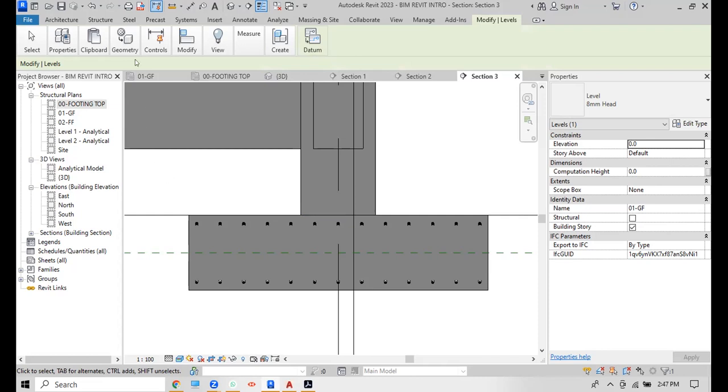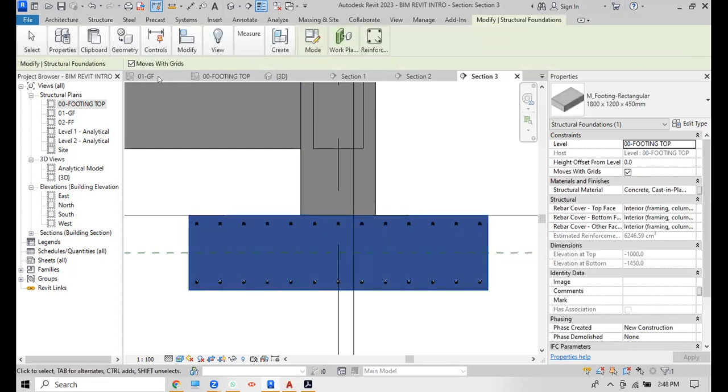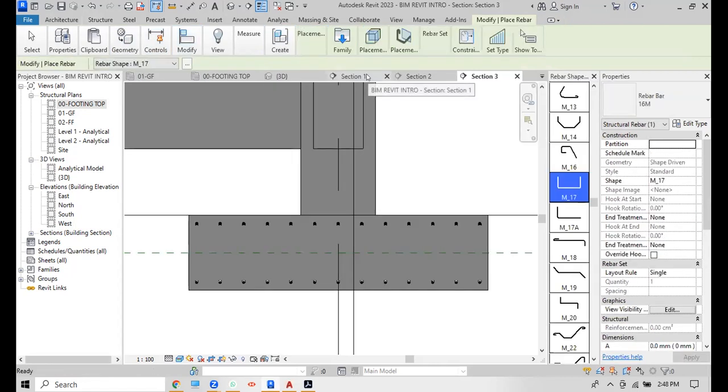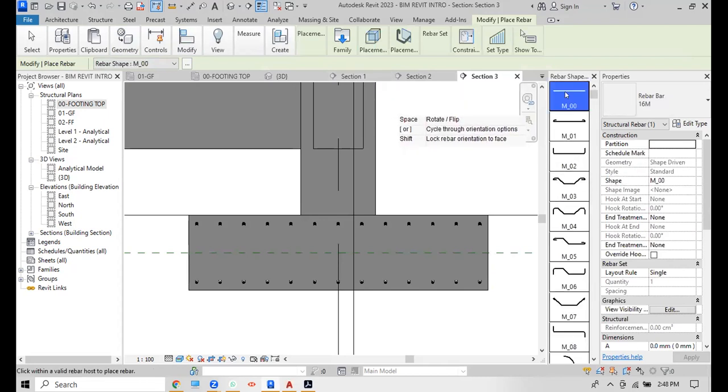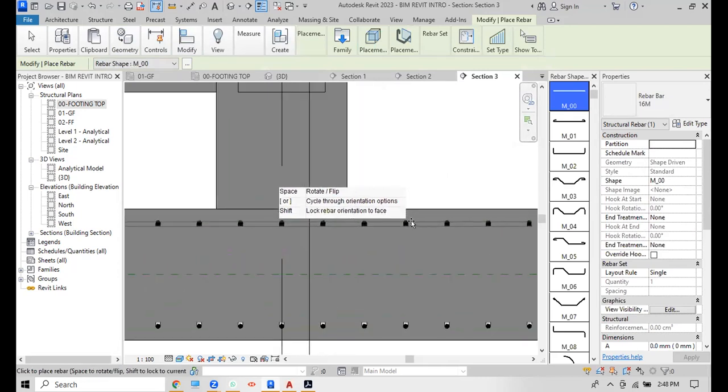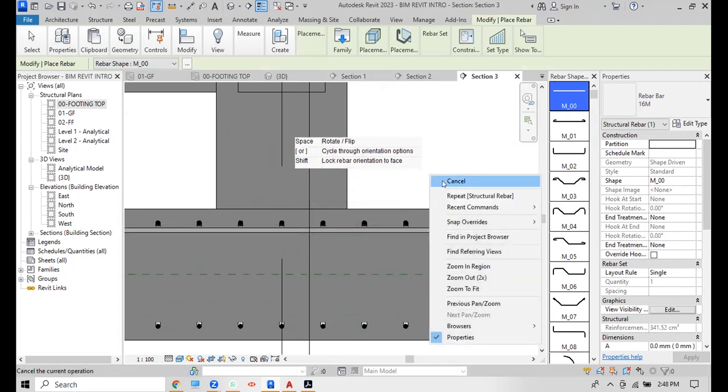So now we want to provide reinforcement. The main thing is, if you can place one bar in the project, you can place thousands, no problem at all. So we go here. You can write the steps even. One step, clicking the member. Second step, going to reinforcement, rebar. So now I want to provide, first I provide a straight bar. So I bring it here. You can see the bar is appearing above that. I can bring it down or anywhere, wherever I want to place. So it is like this.